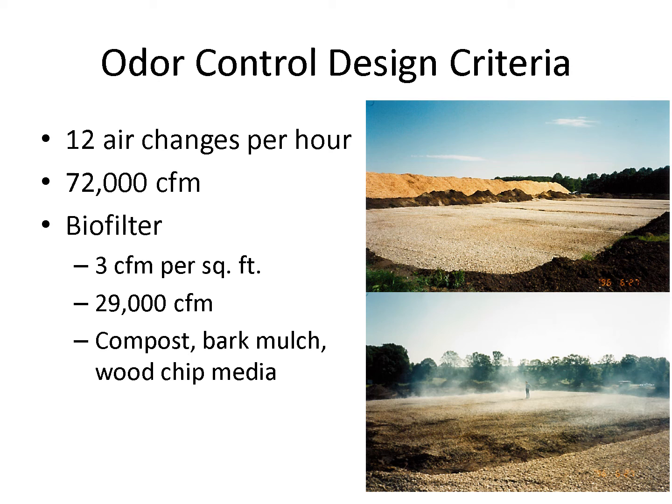Interestingly enough, we have found that after anaerobic digestion, we think, and we've done some pilot testing that shows that we can compost our biosolids after anaerobic digestion on our fairly forgiving site in South Auburn without having to utilize our odor control system. That's currently something we're working through with the Maine DEP, and we'll see how that turns out.